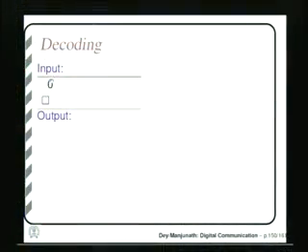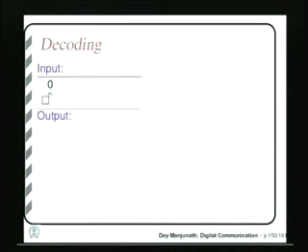So decoding, we are getting the encoded code word. So we maintain the same list, we keep constructing the same list as the encoder is keeping. We can guess from what code word we receive. So we keep doing that. First the list has this null, we know that the encoder keeps null first. Then we receive 1, that is the encoded bit stream coming from the source. 1, we know that we have received 1. So 1 means first null, and then null will be there anyway. So first 0 will be there, 0 1. So we know that the first bit was 1. So we keep 1. Then we receive 0 0.